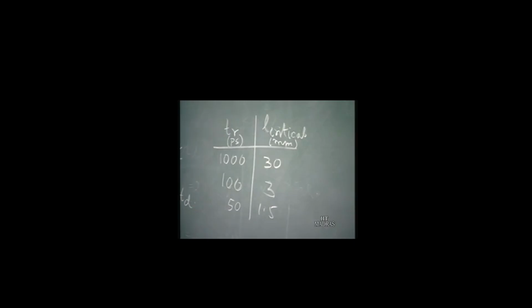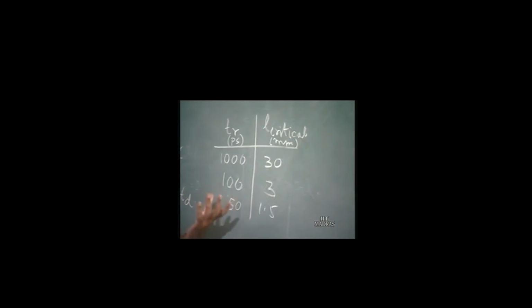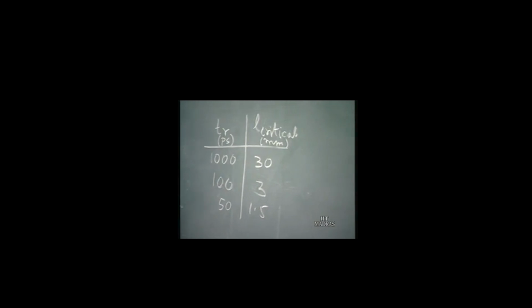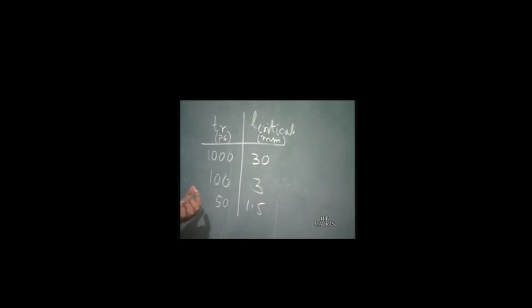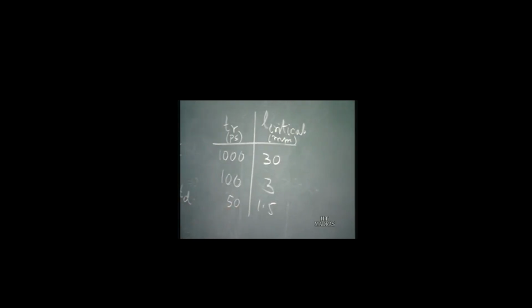Now these values, 100 picoseconds and so on, are not so uncommon nowadays. We have rise times and fall times of this order. So for 3 millimeter, if you have something on a PCB, of course, we have to be very careful. We must consider the transmission line effects. Even in very high speed circuits, we may even have to consider transmission line effects on the chip.